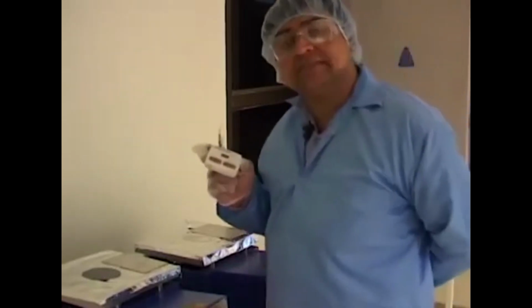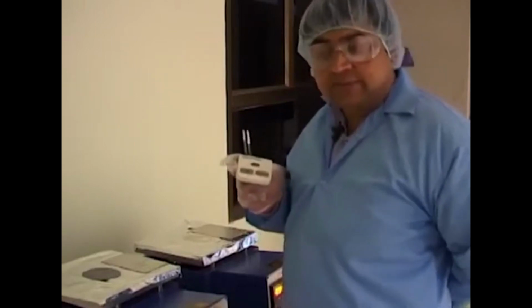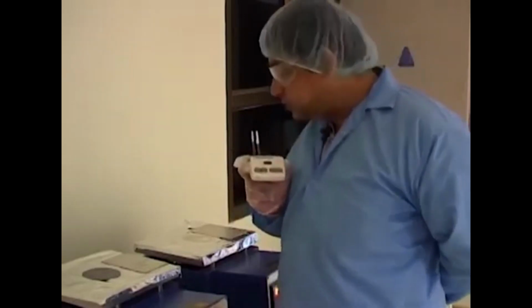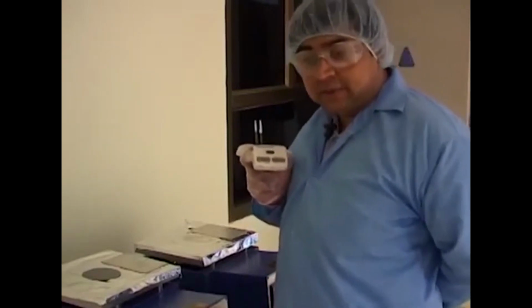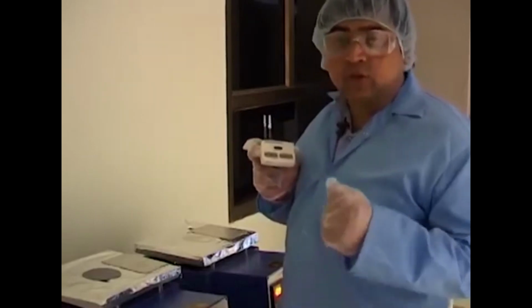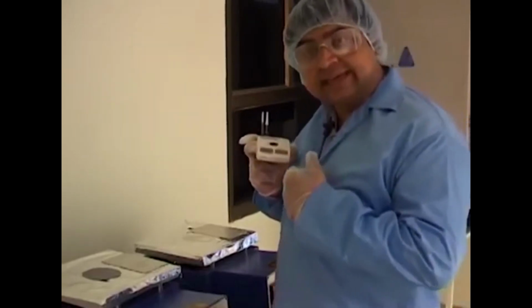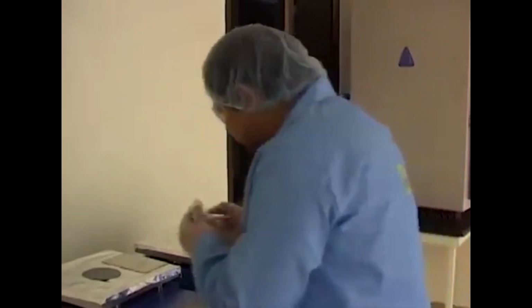Now this is actually an alarm system. It would tell you in advance as the time is over. It will have a beeping sound from which you can figure out the exact time for which the resist is being heated. The thing about microfabrication is that you have to be very careful about the exact hold temperatures. This right here is an illustration that the time is over. So we will go ahead and pull out the resist coated wafer now. Again the same precautions need to be followed.